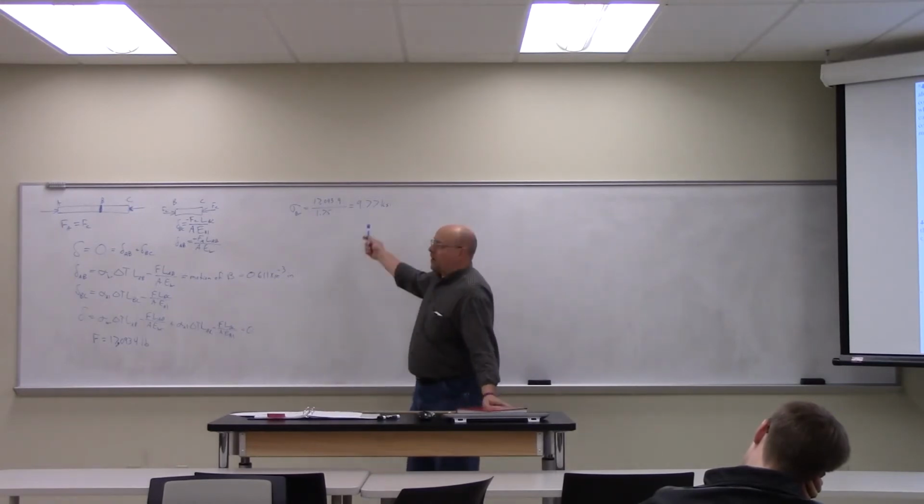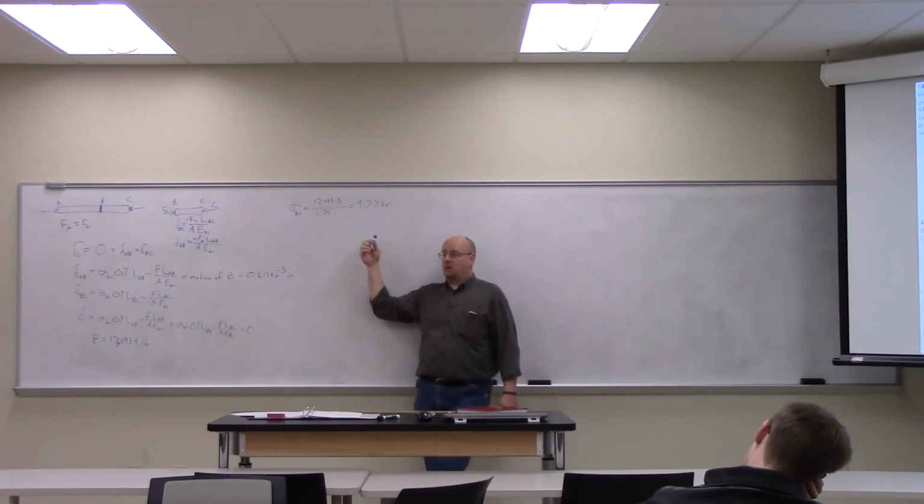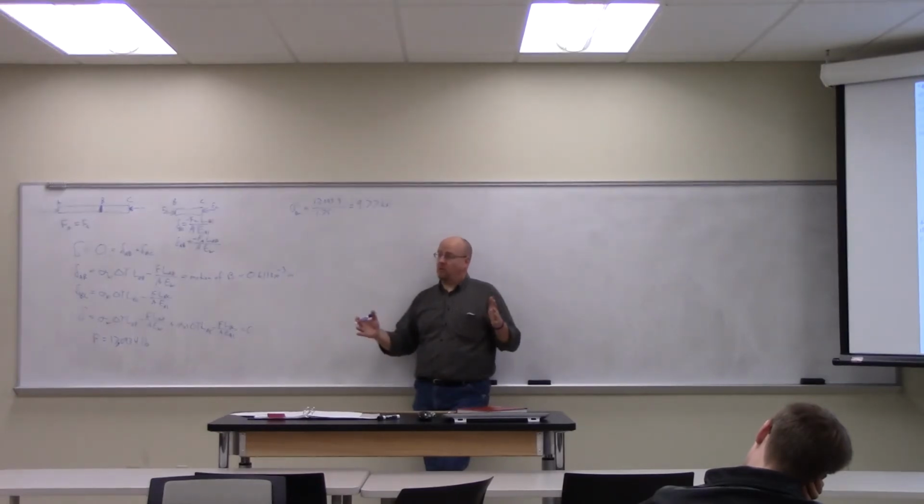But if this number were 12 KSI, then when I cooled it off, it would try to shrink back beyond what its original dimensions were, because I would have compacted it. It would have yielded, with some kind of compression and corresponding bulge.